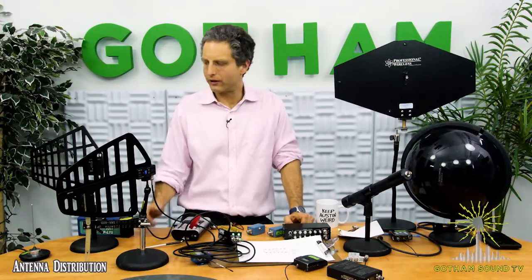The thicker the cable, the less the loss through the cable, in general across all frequencies. But the thicker the cable, the more of a pain it is on set. So that's going to be a balance. And I think it's a fair trade-off if you're going to set the amplifier at the antenna and you need to use slightly thinner cable because you're needing to coil it up and pay it out and coil it up constantly. That's going to be part of the equation that you think about.